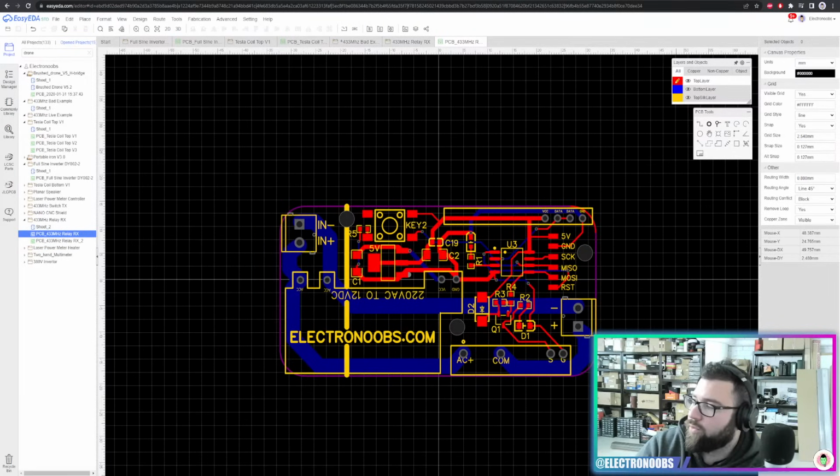The sharp angle track is okay as long as the signal is below 1 GHz. Thank you for that tip. I didn't know that it was that high. I thought that with megahertz you would already have problems, but I trust you. So if you work with low signals like maybe 1 megahertz, you don't have to make 45 degree angles. But for example, for 2.4 gigahertz, like maybe a radio connection, you should work with 45 degree angle tracks.